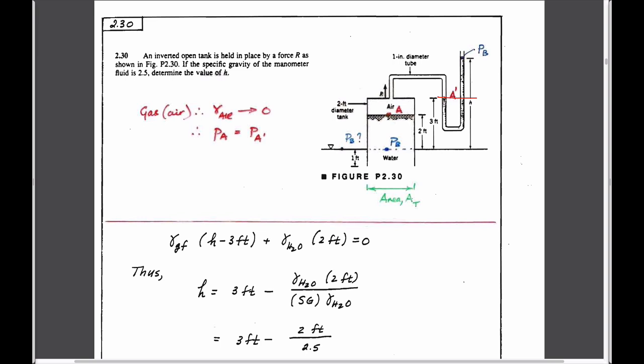And by definition, the pressure here has to be less than the pressure here because there's a column of gauge fluid above it. And so this isn't really the correct representation of the pressure in here. You'd expect actually this level to be lower than this level. However, having said that, we can still work with this initial configuration. It's just that when we calculate the height of this manometer column, it will turn out to be maybe lower than this height if that's appropriate for this particular example.